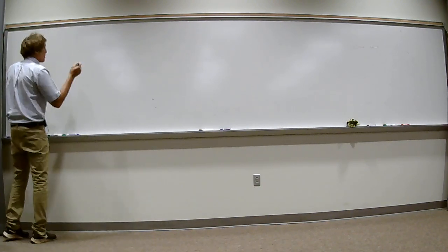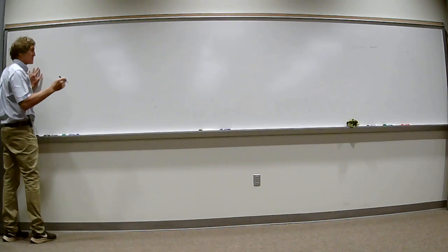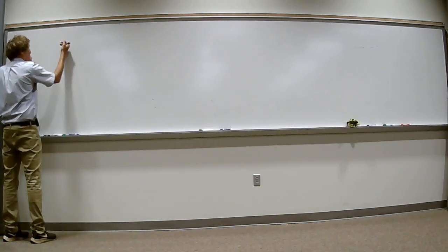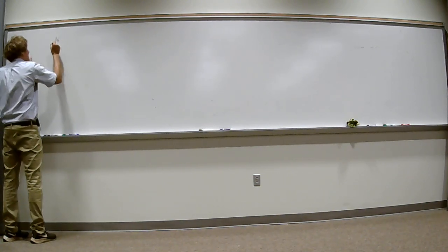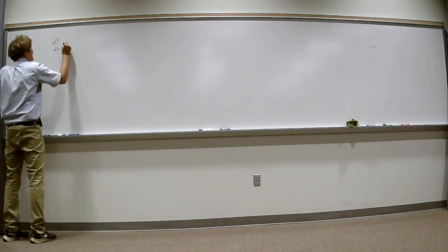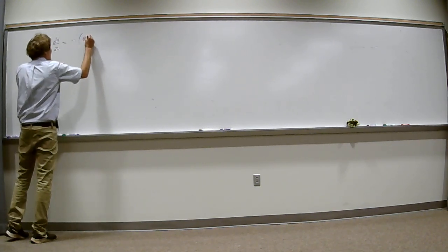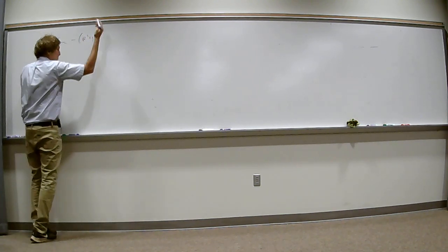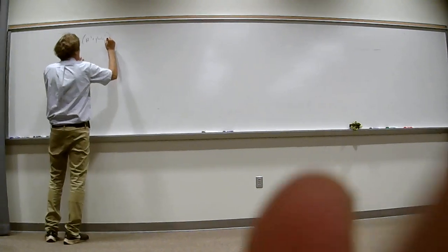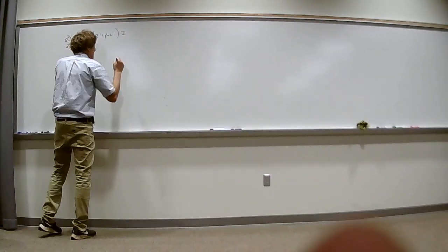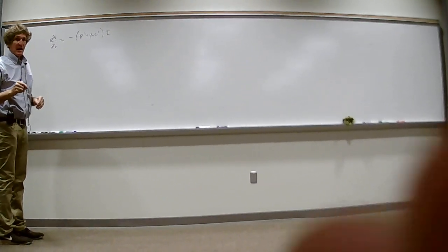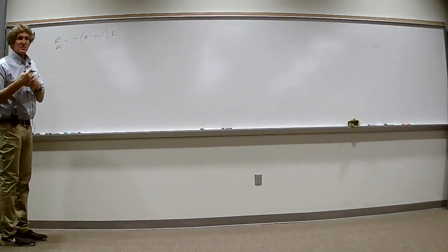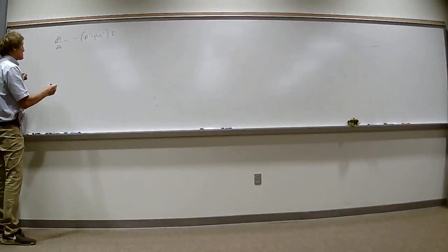So now we're going to go ahead and talk about characteristic impedance. So we start, and I'm going to start this way. Remember that I had dV/dz is equal to minus (R' plus j omega L') times I, right? We're going back to that differential model. Now, I'm going to do this for just the positive going portion of the wave.